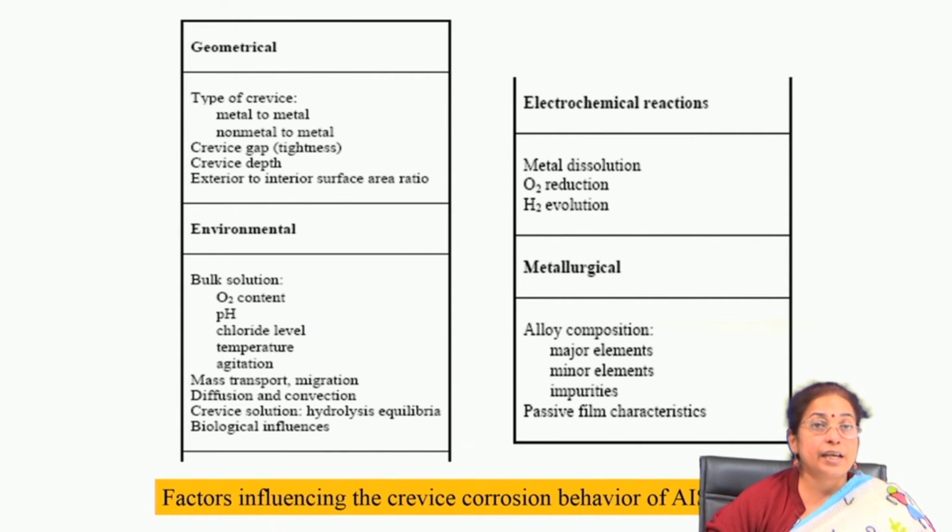As you go on changing the depth, you will find that the attack rate is usually higher at depth, because on the surface the attack rate is much lower, because it is exposed to the environment. So, there is the possibility of oxide layer formation, and as you proceed towards the depth, there will be less oxygen supply or less air supply, as a result of which there is more tendency for crevice corrosion.